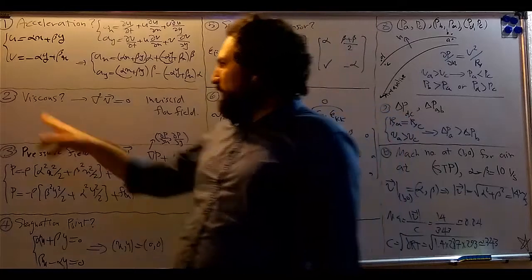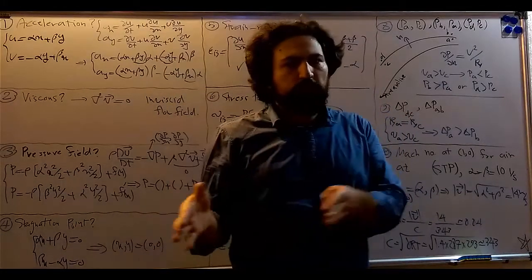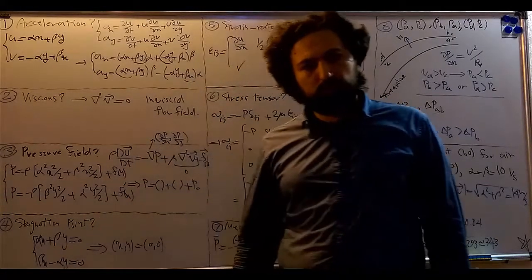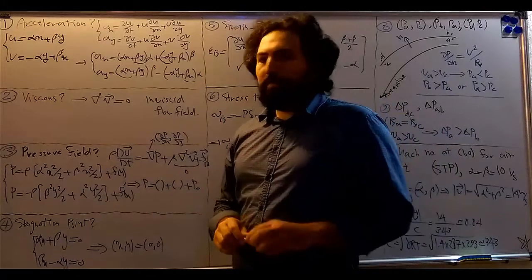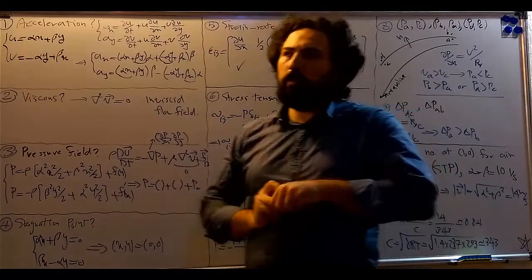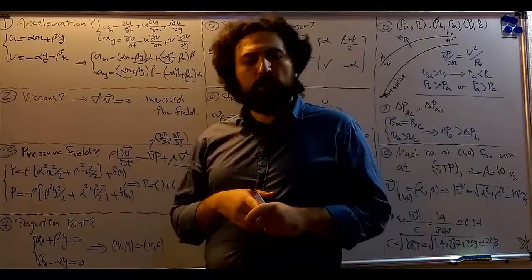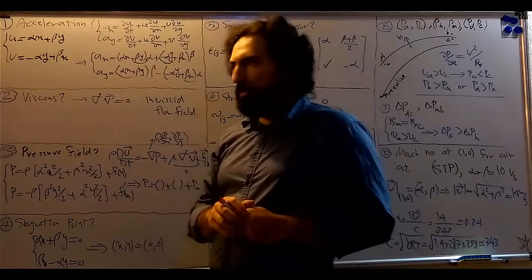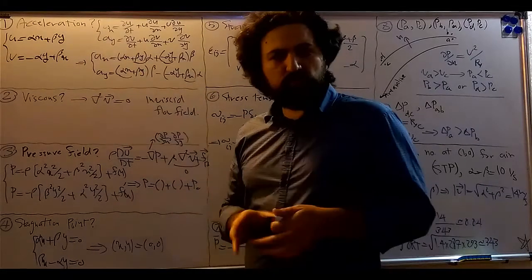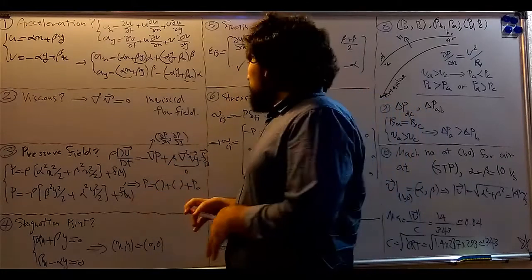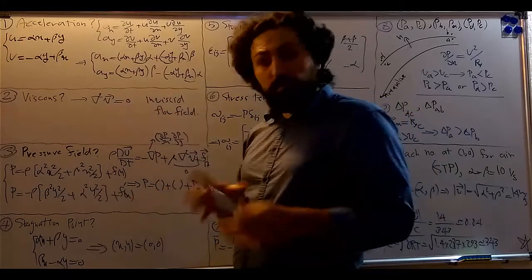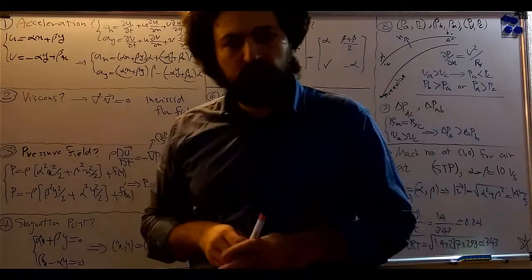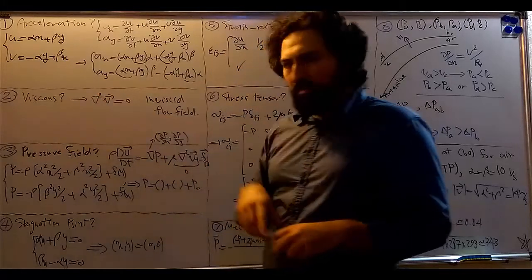The answer to the second question, is this velocity field viscous or inviscid? You have to compute the viscous term in the Navier-Stokes equation, which equals the Laplacian of the velocity field if the viscosity is constant. So the Laplacian of this velocity field is 0 because all terms are linear and the second derivatives of all terms will vanish. So this flow can be regarded as inviscid flow because there is no trace of viscosity in the Navier-Stokes equation, because the Laplacian of the velocity is 0.